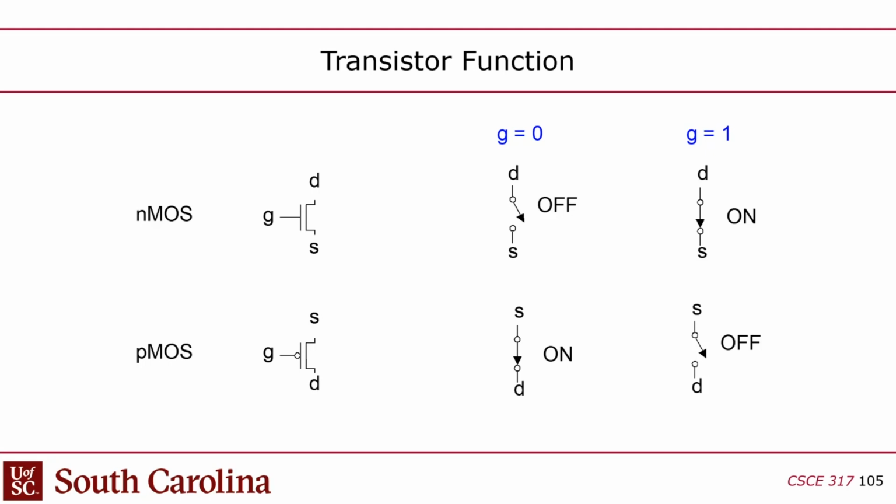You might already know this, but there are 2 types of transistors, an NMOS and a PMOS. In digital logic, they're just treated like switches that are on or off. You've got 3 terminals here. There's actually 4 terminals, but one of them is implicit. It's not shown on the schematic. There's a source and drain, which you could think of as essentially the same thing, even though they're swapped on NMOS and PMOS.